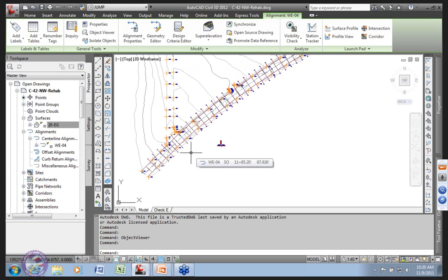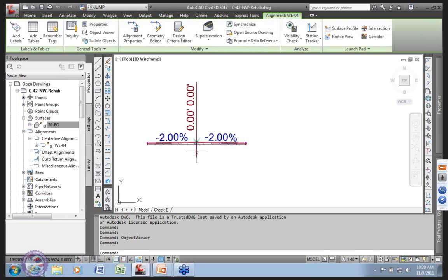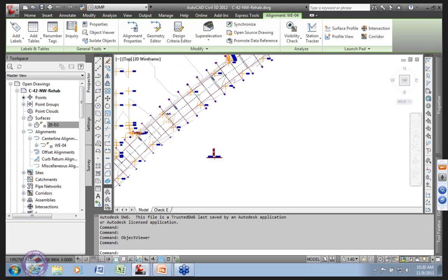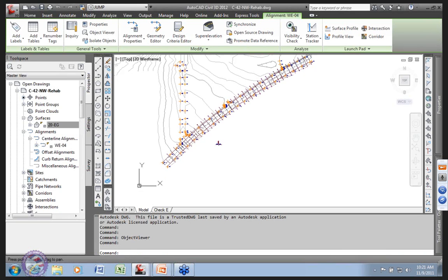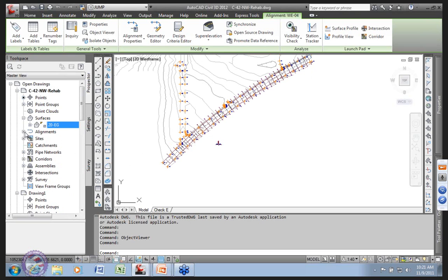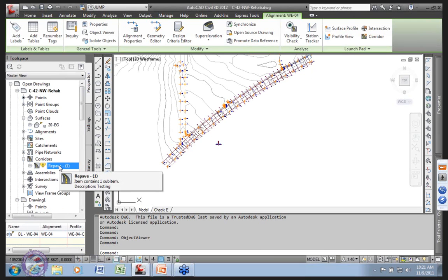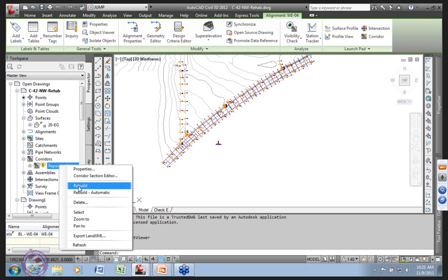So this is an example when we're using an overlay assembly, which we have one here, and we'll climb into it in just a second, where we built the corridor, and we've got a quote-unquote design profile that at this point we're completely ignoring. Okay, so here's one of those subassembly weirdnesses. So what did I say? Okay, so we made a corridor, and currently, because I turn automatic off, because I don't want Civil 3D recomputing all my bits and pieces of corridor all the time, and you do that by making sure that's checked off.